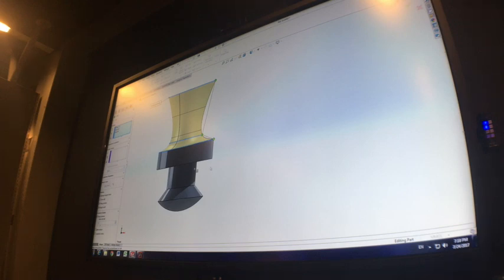For the loft here, we're able to change some of these other settings. So if we look down the options here on our loft, the next box down, start and end constraints, is the one we're going to look at. So start and end constraints controls the shape of your loft at the start and end point of the loft.